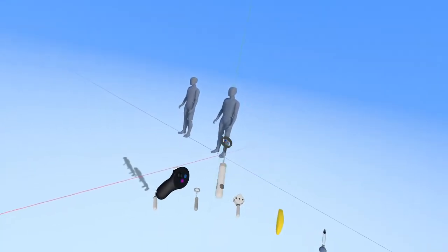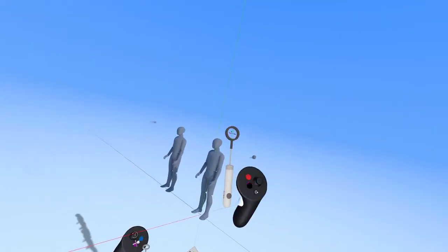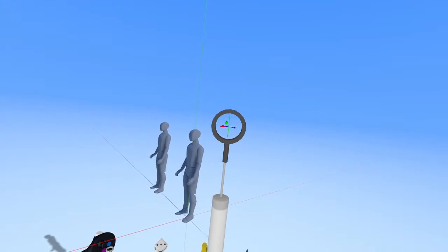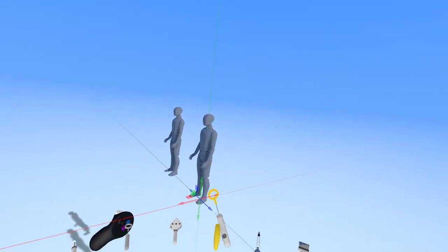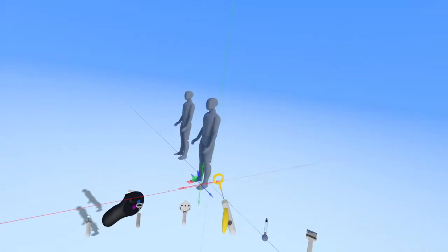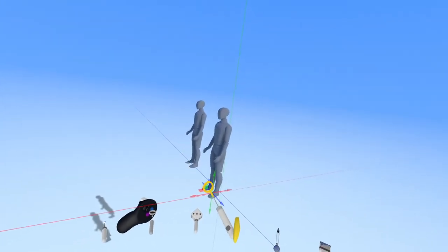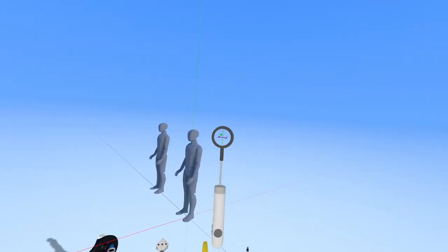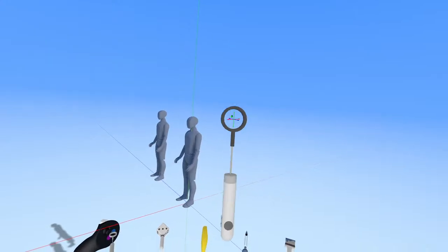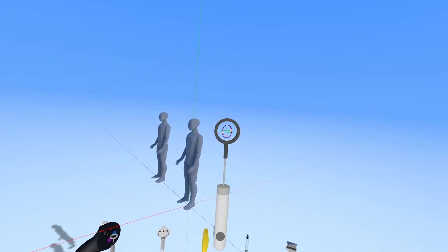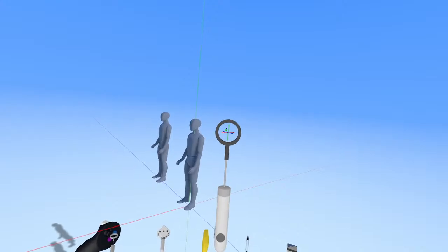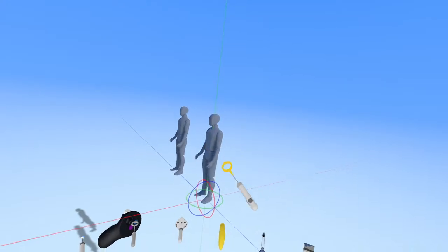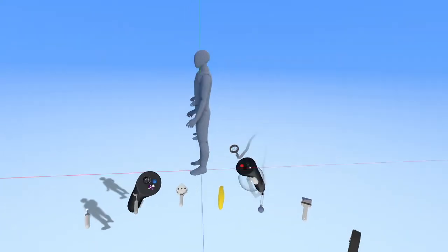So this one, you reach out and you actually grab it like a piece of geometry. And yeah, this is the precision tool. If you look really close there in the center, right now it's on an option for basically moving precisely along an axis or along a plane. That's pretty great, but we want to use rotation, so while holding this, we're going to flick the joystick on the right-hand controller to the left or right, and that's going to allow us to toggle from movement to rotation. And now we can just click, point, and let me get to a better position here.